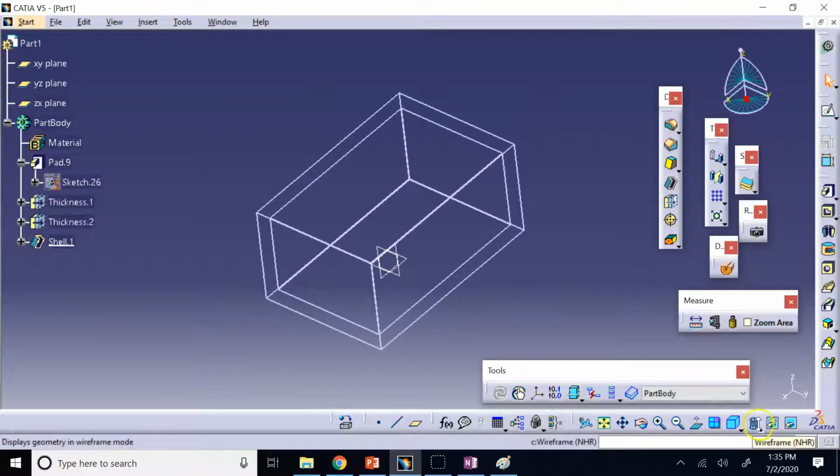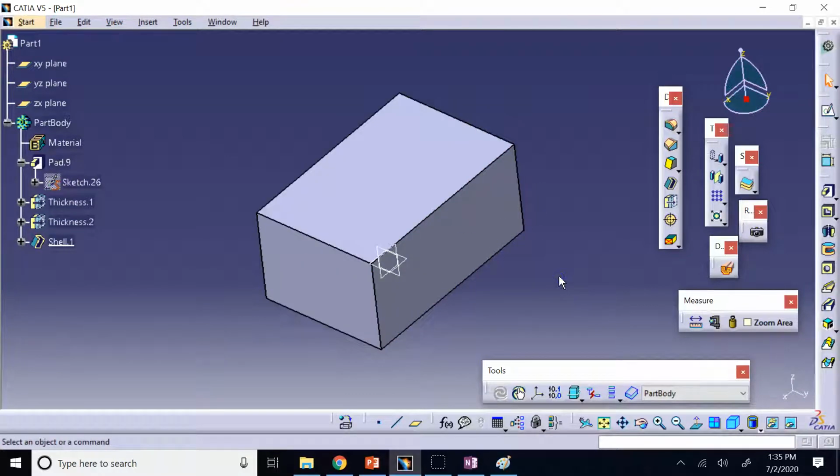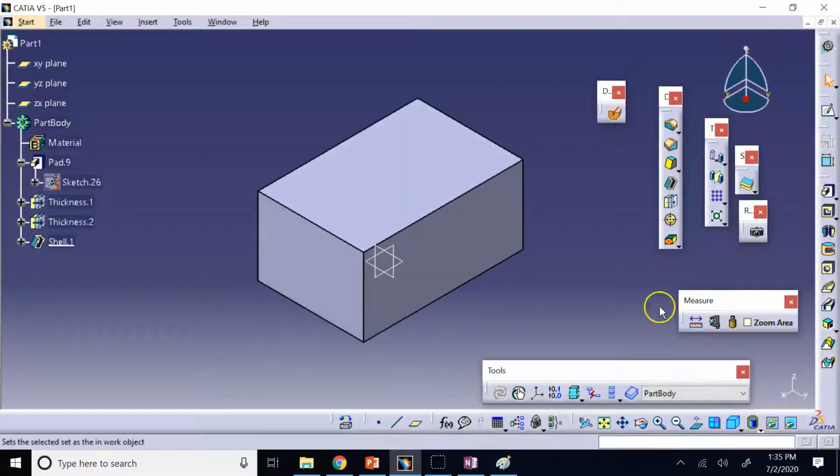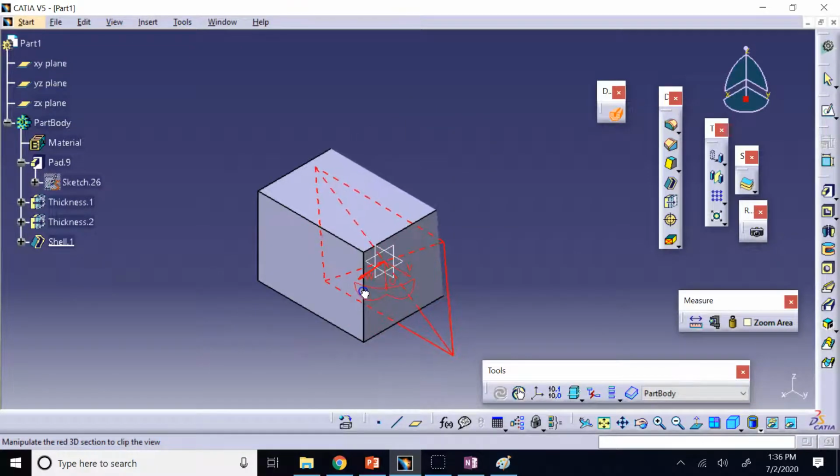And how else can you tell whether this part is hollow, other than looking at wireframe? One of the tools that I wanted to mention later, but I guess it's good to mention right now, is this dynamic sectioning, which I really like. So it's a virtual sectioning. You really do not cut the object, you just virtually do to see inside it. So I say I want to cut this object using this plane, and maybe you want to rotate this plane and make it vertical like that.